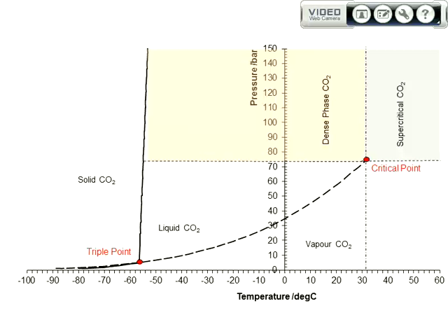Okay? So this is really tedious, because it means that if you are somewhere on this pressure axis, and you change the temperature, you're going to change the phase of the fluid. You don't really want to be operating a multi-phase pipeline, certainly not a multi-phase onshore pipeline in the UK.